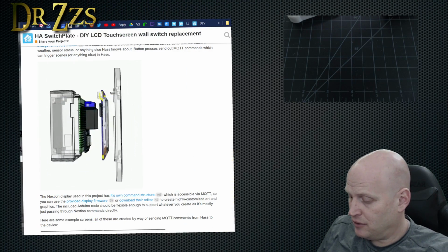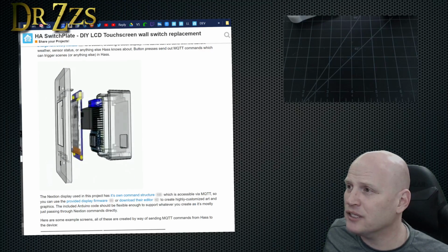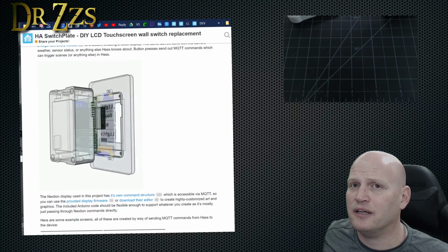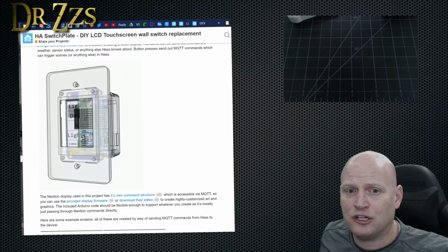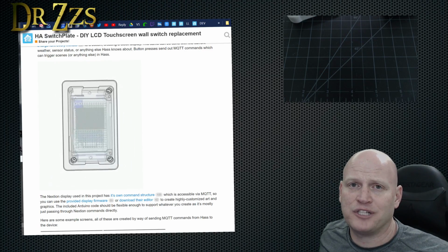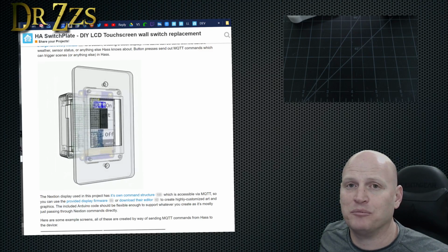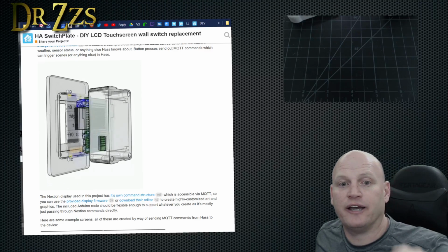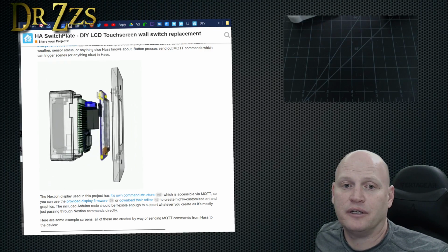Let me tell you. If you're going to do the 433 megahertz ones, the important thing is to find sensors that will send two signals, an open signal and a closed signal. You saw my RF video, and the sensors I had at the time, which are still the only ones I have, only send one signal. So it'll tell you the door is open, but it won't ever tell you if it closed. The Kerui ones that J After Dark is talking about are good.